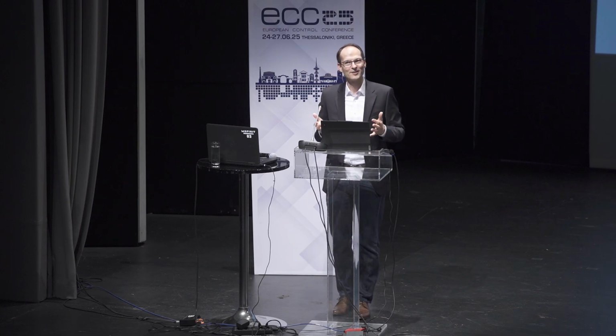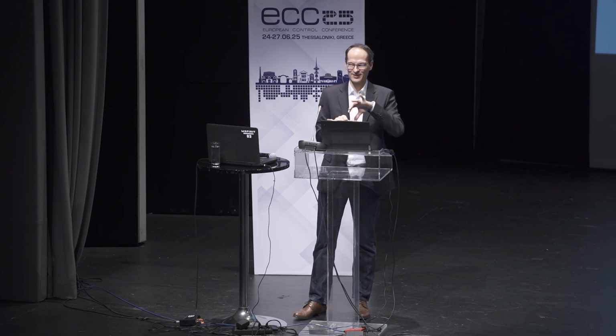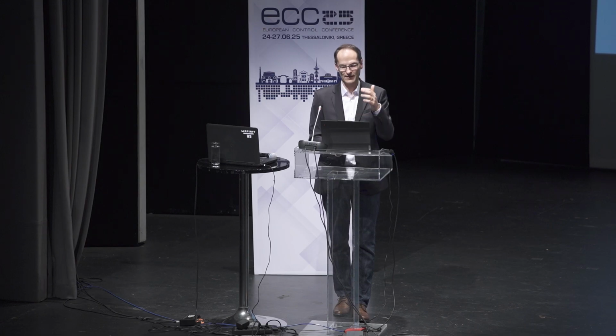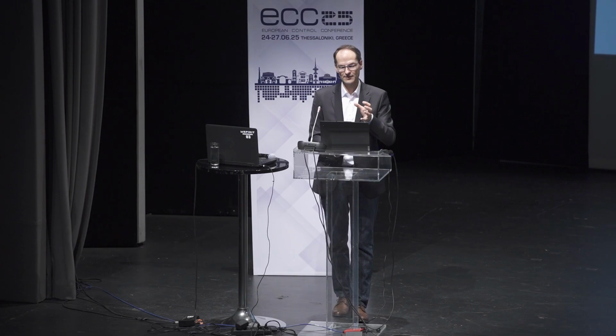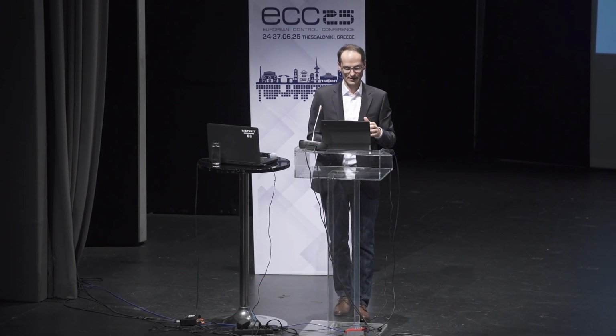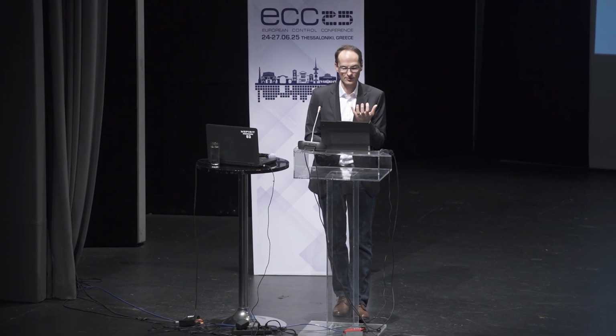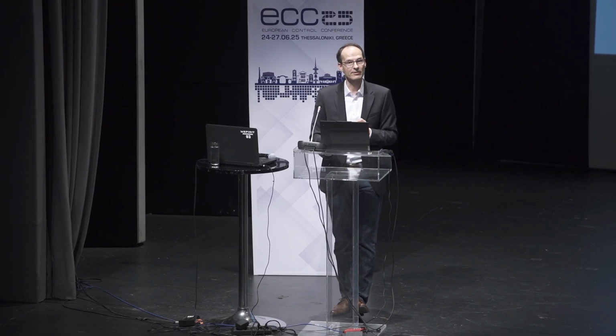And the prediction model is trivial. It's two integrators in two orthogonal axes. So all you need to do is, you have an error now, you want this error to be close to 0 at the end, and then you have a linear combination of your switching time modification weighted with the sign of the switching transition, transformed from the 3 phases into this stationary orthogonal coordinate system you see here. And this you want to minimize. So this is a quantity you penalize in your quadratic cost function.